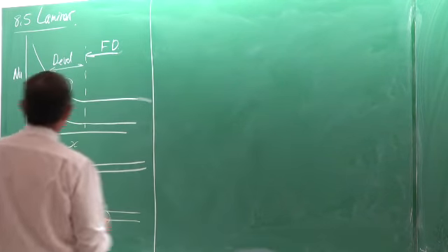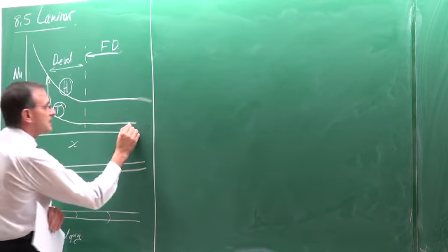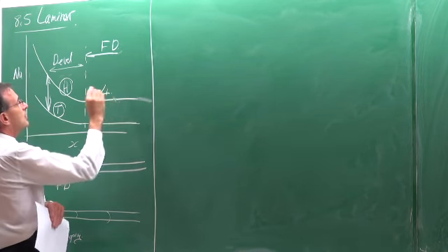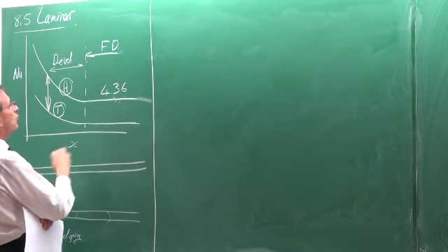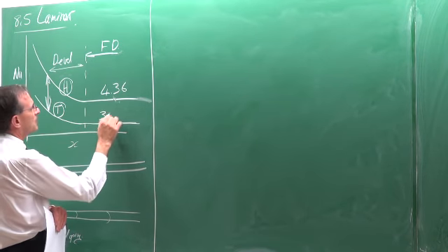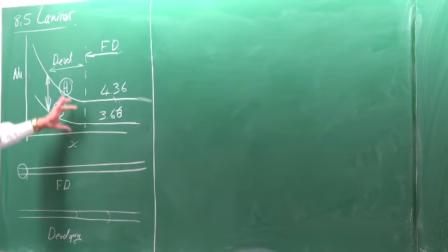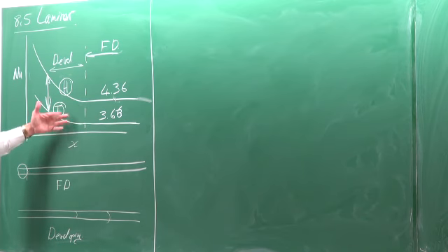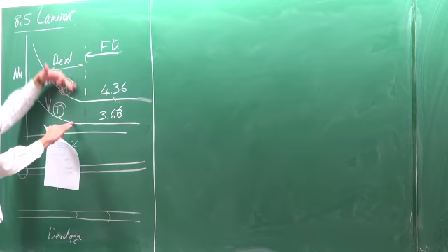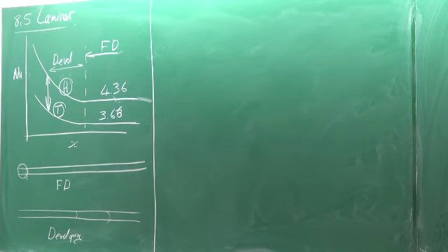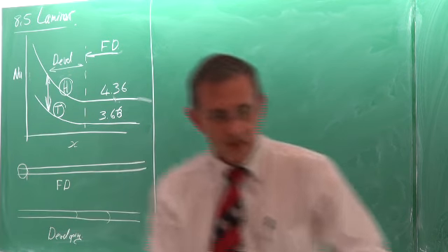Now, a very good example is the case of the constant heat flux, where we've got the Nusselt number of 4.36, and for the constant wall temperature, where it is 3.66. This difference doesn't look like much, but it is about 30% if you look at the values, and specifically in laminar flow, these values can actually be much higher if there's also secondary flow in the tube. So there can be quite large differences.